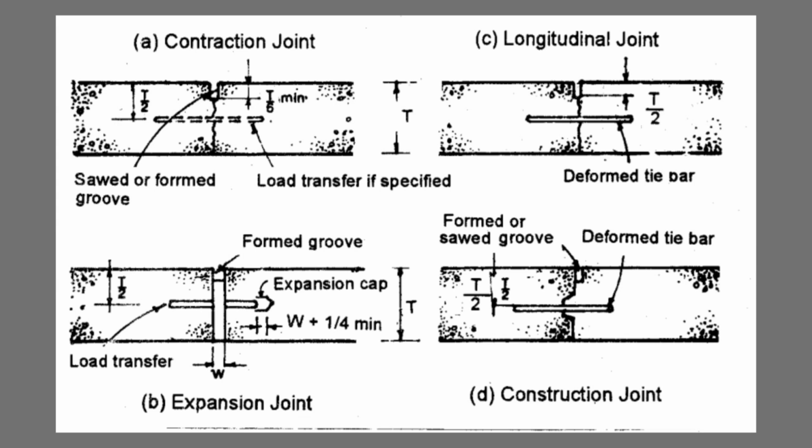As you can see on the slide, there are different joints, such as the contraction joint, a weakened vertical plane caused by a groove that was ripped, molded, or tooled into a concrete slab. By controlling dimensional changes in the slab, it controls where cracking occurs. Next is the expansion joint. An expansion joint is an assembly designed to hold parts together while safely absorbing temperature-induced expansion and contraction of building materials and vibration, or to allow movement due to ground settlement or seismic activity.